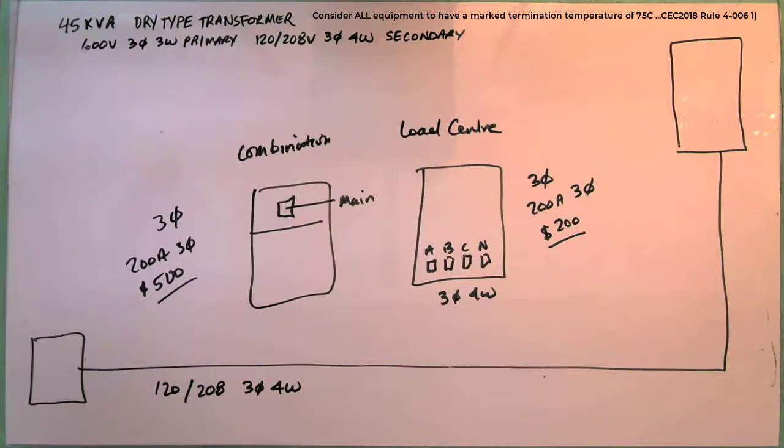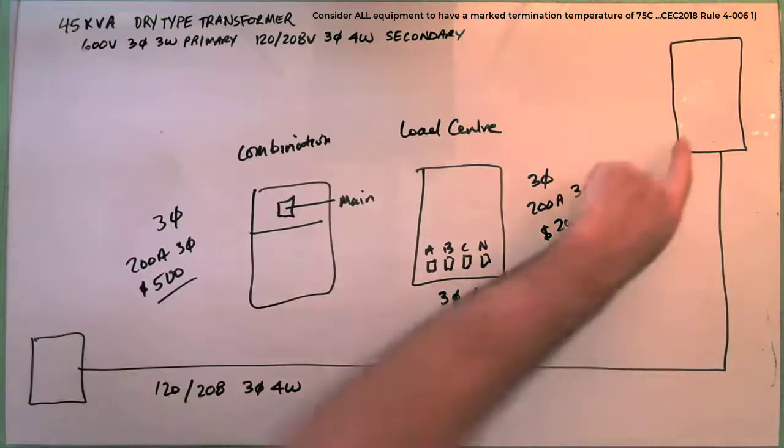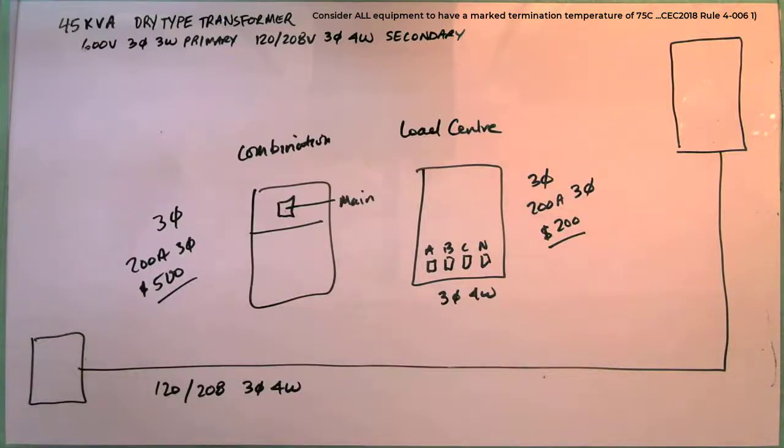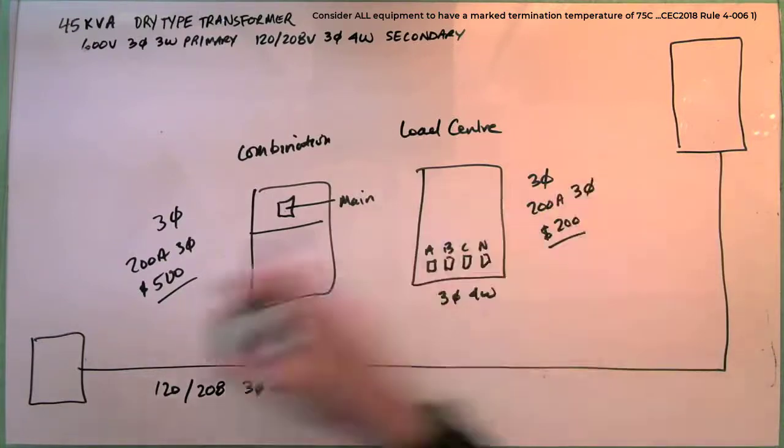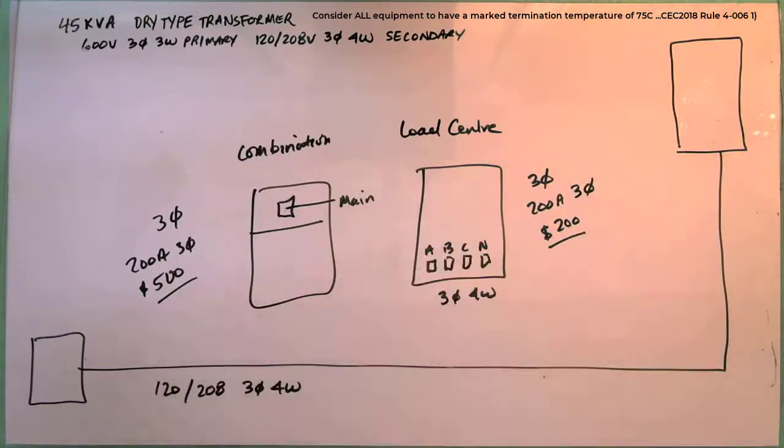Sometimes you get defects and you learn. I got a defect one time because I did this. I put a disconnect and the transformer in the electrical room, and I ran this all the way to the bank, and I put a load center in the bank. Defect. Is that electrical room accessible 24 hours to the tenant? No. Then you're going to need to put a combination panel. So I pulled out the panel and put in the combination, and I ended up using this somewhere else.